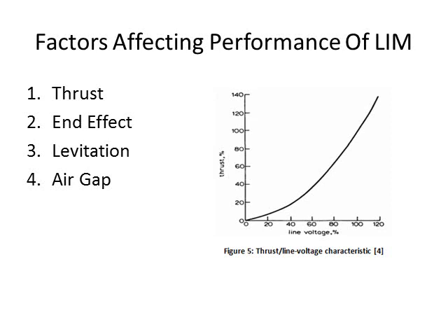and is analogous to an induction motor with a high rotor resistance. The second factor is the end effect, which refers to the phenomena whereby magnetic energy is lost at the end of the primary by the relative movement of the primary and the secondary. It is undesirable and causes loss in performance and efficiency.